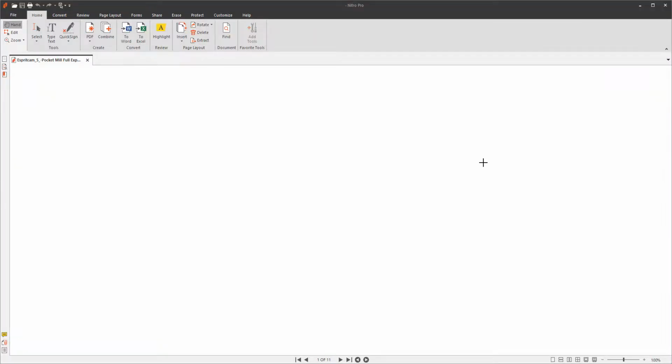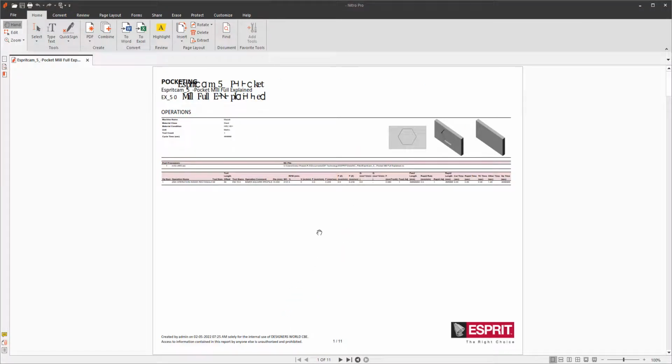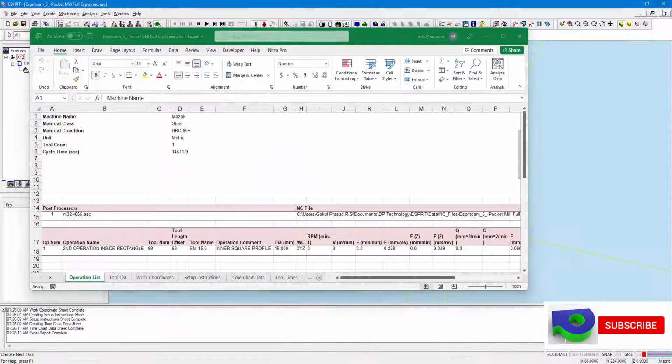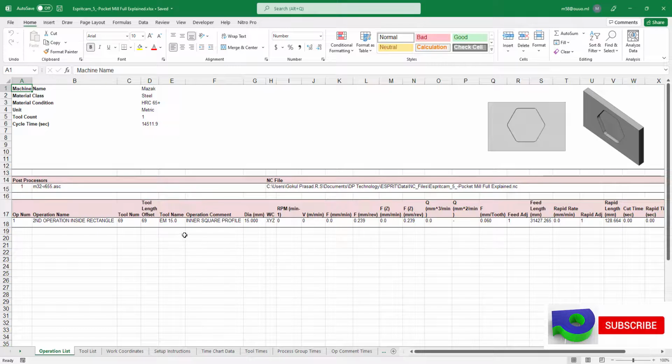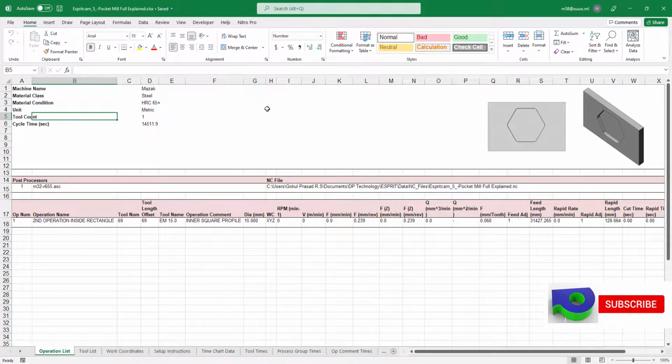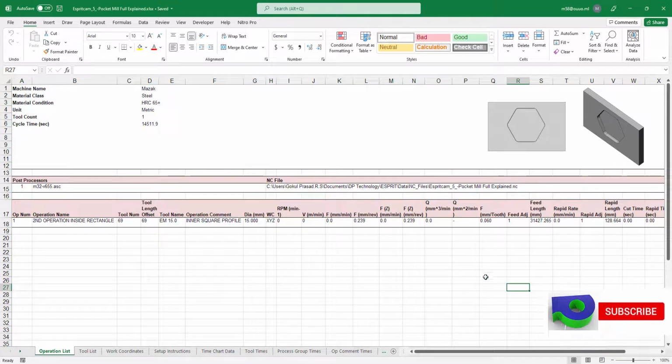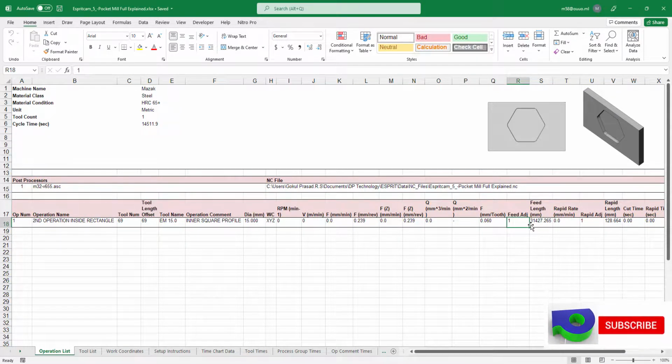the product which you developed in the CAM, and you can also optionally get this as PDF. Okay, so I just close it, and this is my Excel. You see the inputs we have given on the report which I just took, and it has only one tool operation, and it says what feed rate is given, what the speed is, what diameter is used, what the RPM is, and those details are given in detail here.